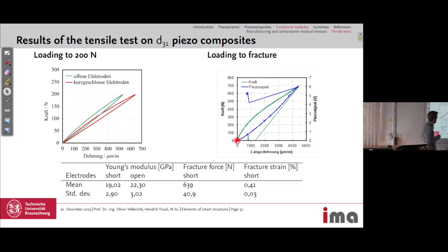see that in green there's the signal from the strain gauges going up this way, and we have a similar signal from the piezos, but with a curvature the other way around. And here at this point we have a failure: the strain gauges disconnect, so we don't have a reading anymore, and also the piezo breaks, so we don't have a reasonable signal, at least from this point on.